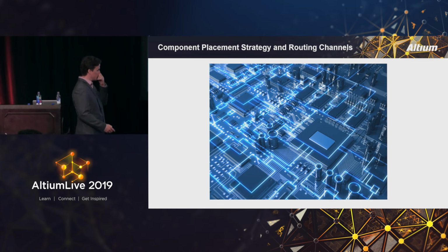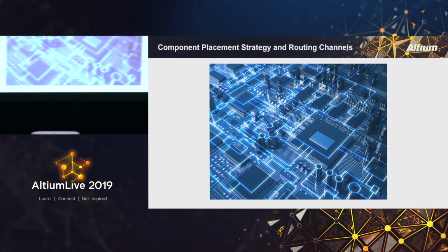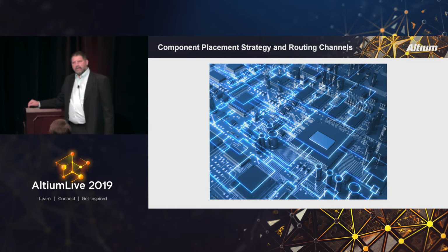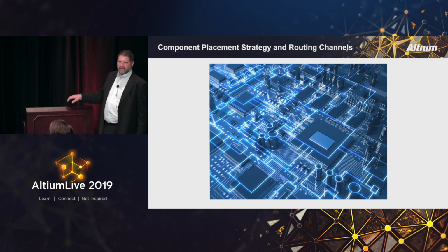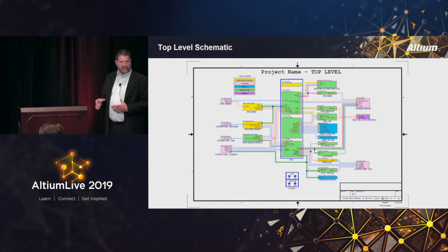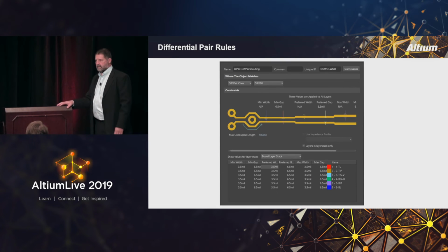One more thing on that. It's easier to modify a placement that's been done in a minimal space than it is to try to fit that into an area that's not conducive to that part. You might do a little bit of modification, but you're almost always better off doing a pre-placement. It gives you a really good idea of how much room you need for that circuit.